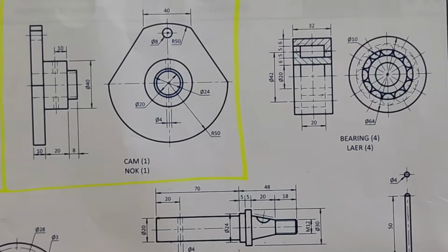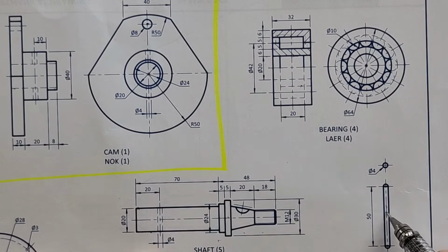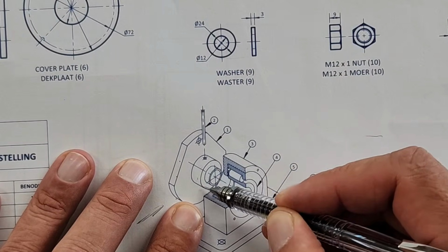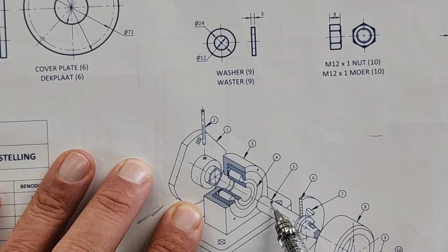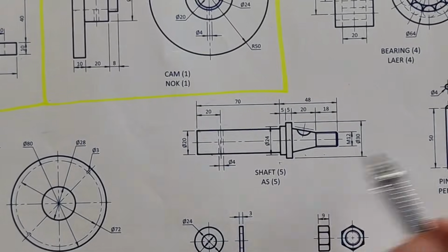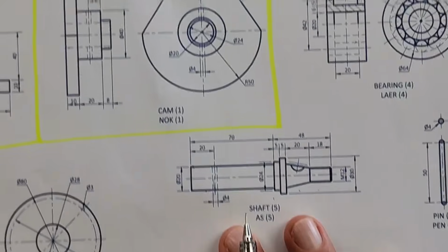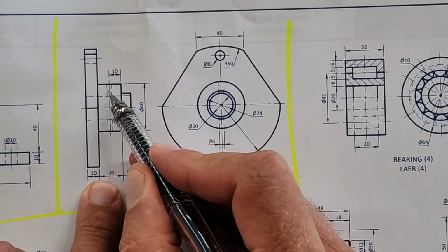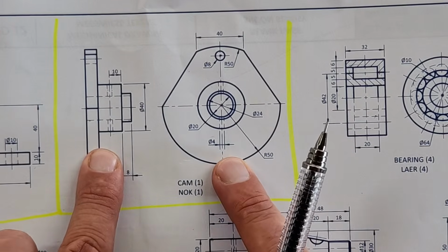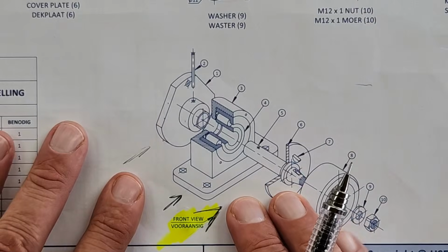Then something that's very important in this view here: that shaft has a hole for this pin to go through here. And you can see that again from the 3D, that pin goes through my pulley. It's going to go through this hole on that shaft so as to fasten the pulley onto that shaft. And I can see that there's the pin, diameter 4. There's a hole, again diameter 4. And look here, on the actual pulley, there also is a diameter 4 hole that's indicated for us. So you're going to have to use the different measurements to confirm what you see in the 3D view.